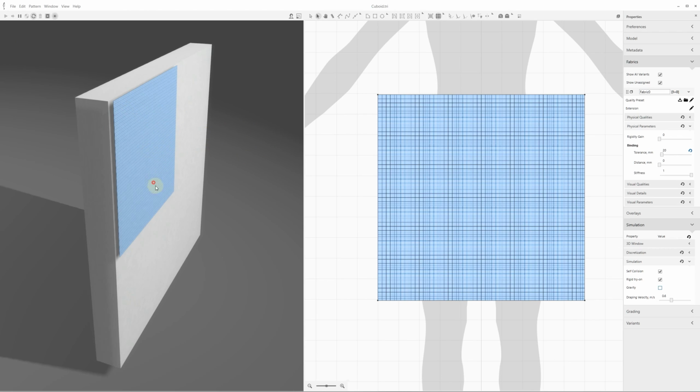In our example, when we start the simulation, we can't move the cloth from its original position anymore. We have our cloth 100% bound and all its faces won't move from their positions relative to the surface of this cuboid. Let's now turn the gravity on and start changing the binding distance and stiffness.